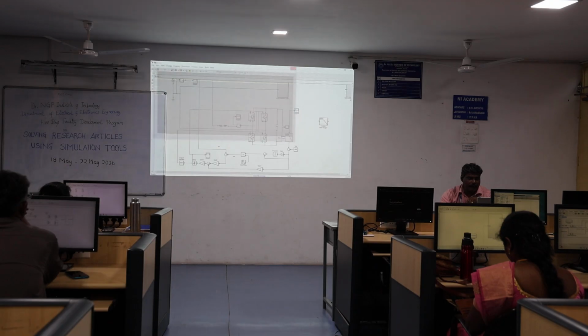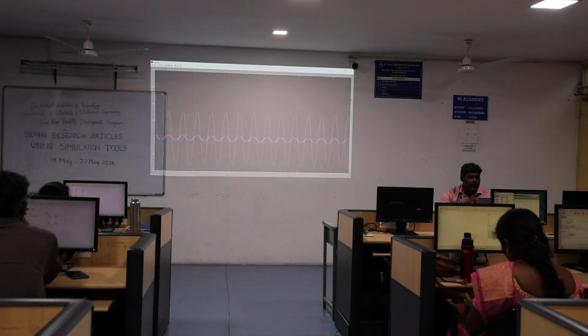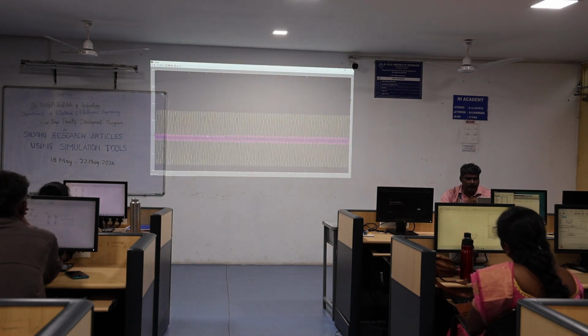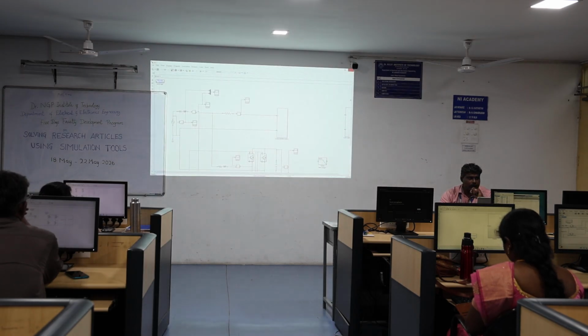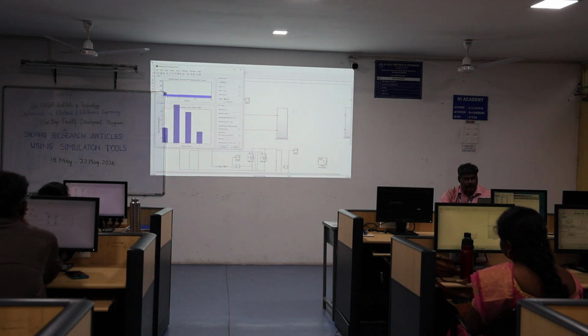Next one is we need to control the harmonics and improve the power factor. Now we are improving the power factor. So you see here, even though the load is varying, the current is maintained constant. So now you can check the THD also. It was somewhat lesser. You can take one cycle, it is less than some value. You can tune some other values, then you will get less than 5%, right? So now you do it.